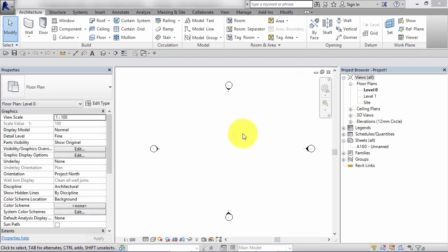In this unit, I'm going to show you how you can bring CAD files into your Revit projects and utilize that information. Now, there's three main reasons why you would want to do this. Number one, you've got, let's say, a building plan or a site survey in a CAD format, let's say DWG or DXF. So you want to bring that file into your Revit project and use that as a starting point to model your 3D design.